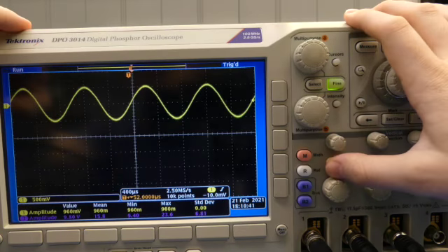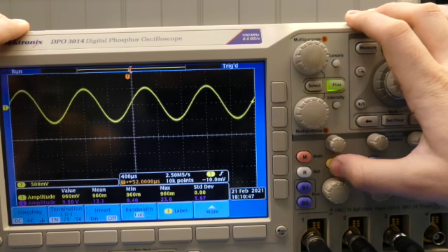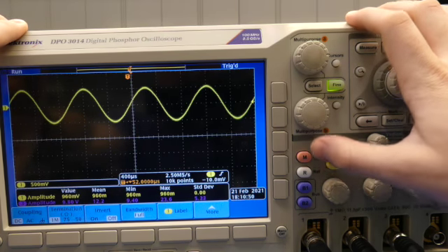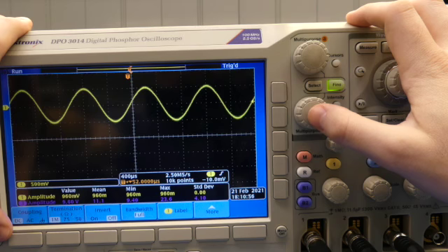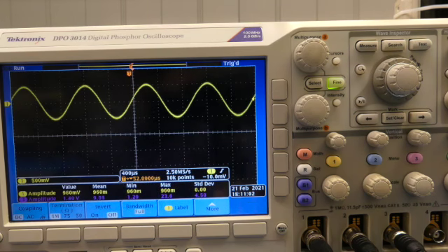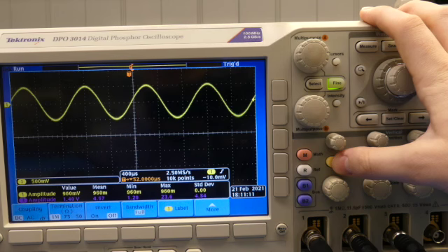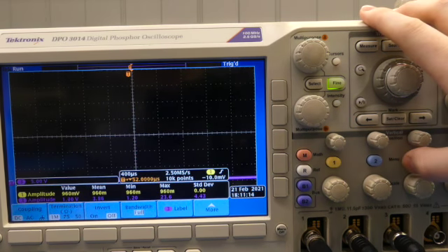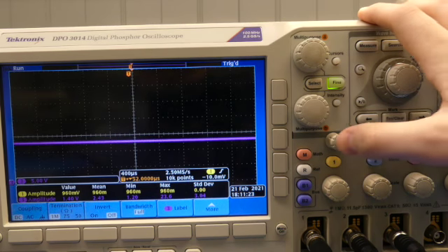And that's DC coupling. Essentially it helps you to tell if there's some unwanted DC component in your system. You can also use the oscilloscope to measure DC voltages in this way by allowing DC coupling. I'll have to do it with the 3rd channel because my first one is plugged directly into my AC generator. If you want to use your oscilloscope to check for DC voltages and read DC voltages instead of having to use your multimeter, you can do that by looking at where this vertical line is.